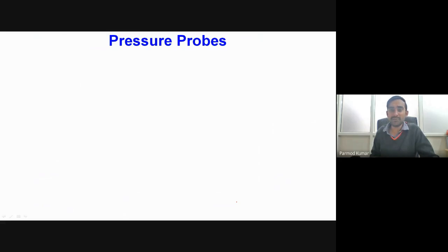Now one very last topic we will try to see in this particular lecture. This topic is mainly oriented towards the placement of the pressure probes. Okay, because in our very first lecture we have seen the measurement of the flow using the measurement of the pressure. So the data of pressure, whatever we are measuring, should be very correct while we are using that data in order to obtain the corresponding velocity field.